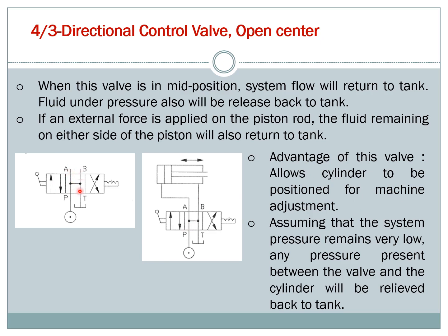When you want to make adjustments to the machine, you just place it in the unactuated position, so all the oil will be returned to tank and you can do the adjustments easily. So this is preferred in industry.